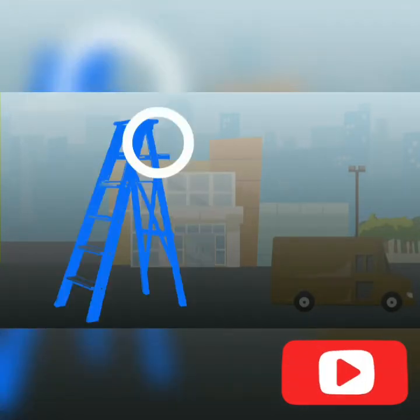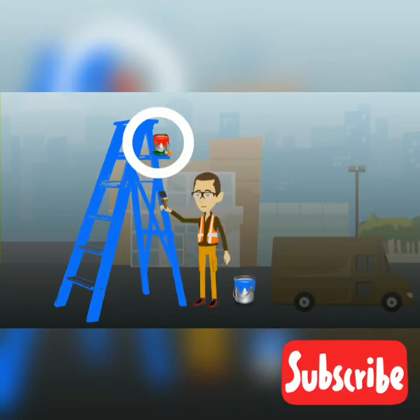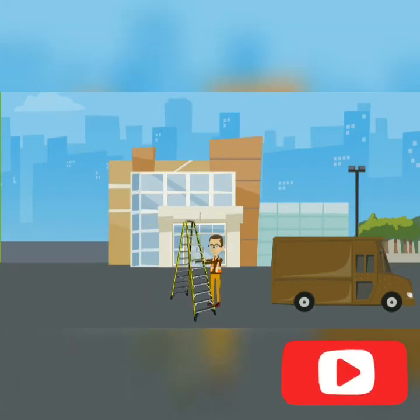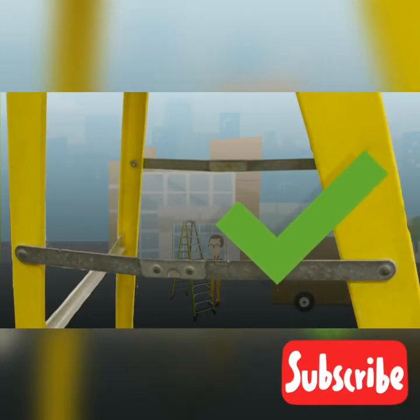Stepladders also include a shelf which can support paint cans or other objects while working. Just like extension ladders, stepladders should always be inspected before use. When opening a stepladder, make sure the two hinged metal braces called spreaders are locked down and are straight.